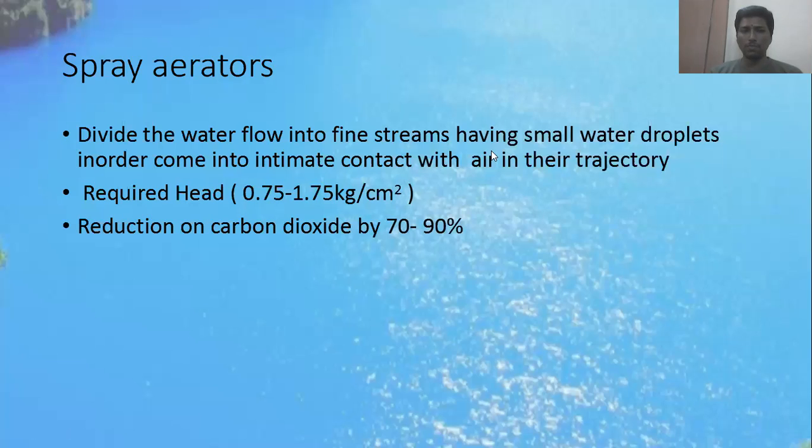There may be chances of malfunctioning, due to the presence of some precipitation-causing reagents or chemicals. Obviously what happens is the nozzle will tend to get clogged, or if algal growth occurs, it will not work in a proper manner, because the diameter of the port which has been provided will be less. So these are certain operation and maintenance techniques to be implemented.